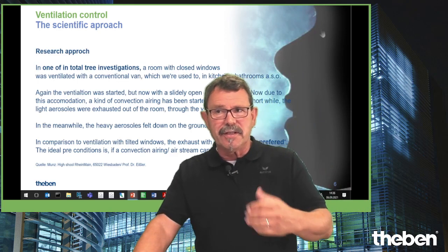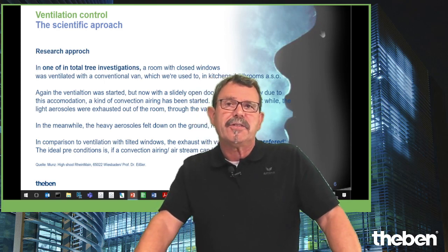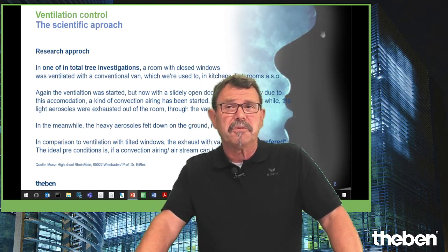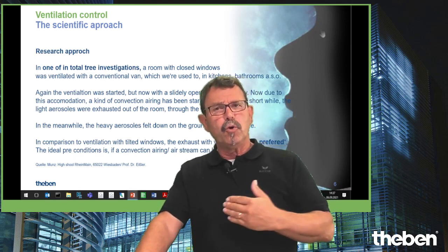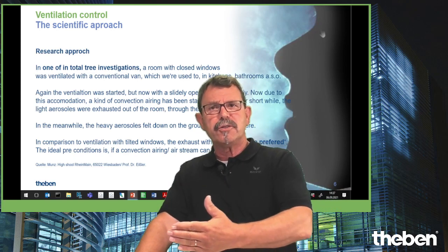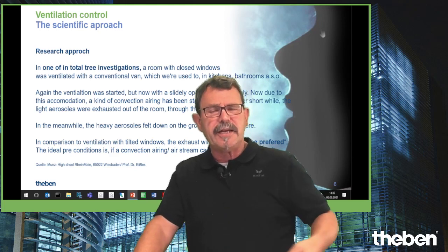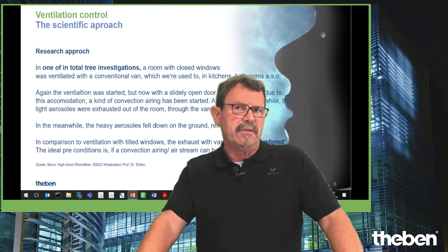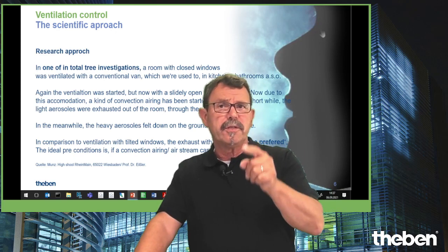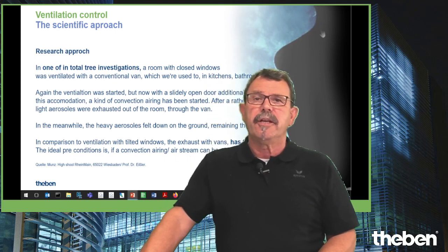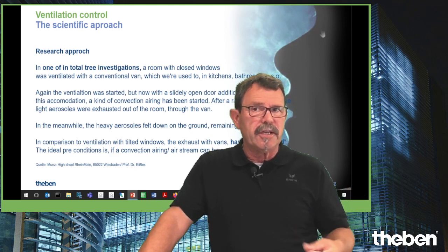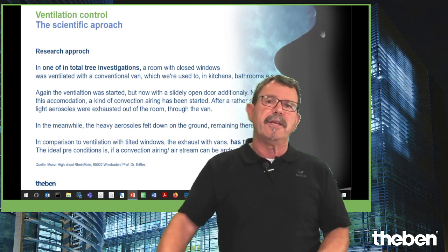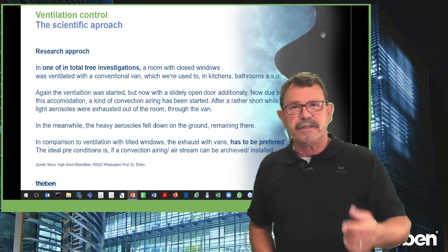And this institute here, this high school, investigated, and just a tilted window was only medium efficient. To open a window is by far better. And if you open either another window or you slightly open the door so that a natural airstream is ongoing, this is rather efficient. Or if you use just a simple fan, built for instance into the wall, this could generate a natural airstream as well and can bring down tremendously the load of these light aerosols.